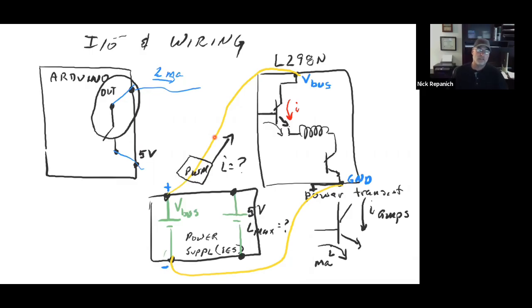In fact, if you look at the wiring that I buy, most of the wiring I buy for everything, 18 is small enough to fit in almost all the screw terminals that you're going to come across. So I'll use 18 even in my control circuits, because it's small enough to fit in there without trying to jam it in. But 18 will also carry, I don't know if you look it up, 3 or 4 amps. It's enough to actually run current through as long as it's stranded. So most of my hookup wiring, I buy 18. You could buy 20, and if you use little motors, but I think if you start getting down to 16, the wires don't fit for universal use.